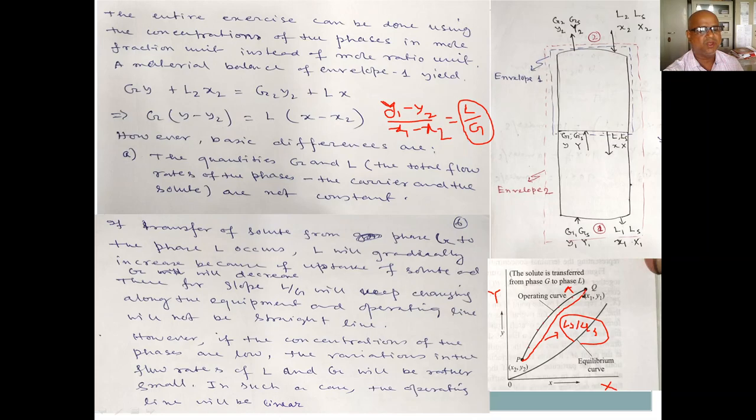But with Ls, the two extreme points will generally be known, so then you can calculate it. So now we understand the advantage of mole ratio, capital Y, instead of mole fraction, small y, in designing. That's why we generally consider capital Y, capital X based on the solute free basis.